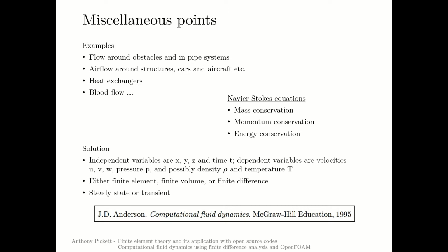They're all based on using the Navier-Stokes equations, which I will briefly mention. These are conservation equations for continuity, that means mass conservation, also momentum conservation and energy conservation. In the solution we have independent variables, in this case positions x, y, and z, and time.